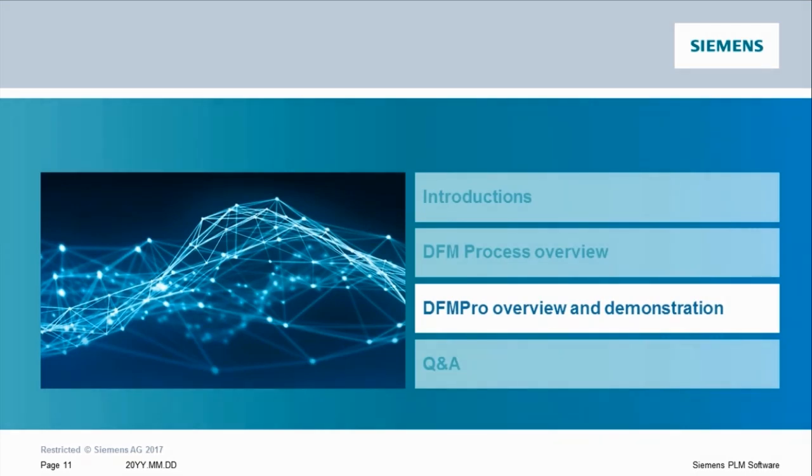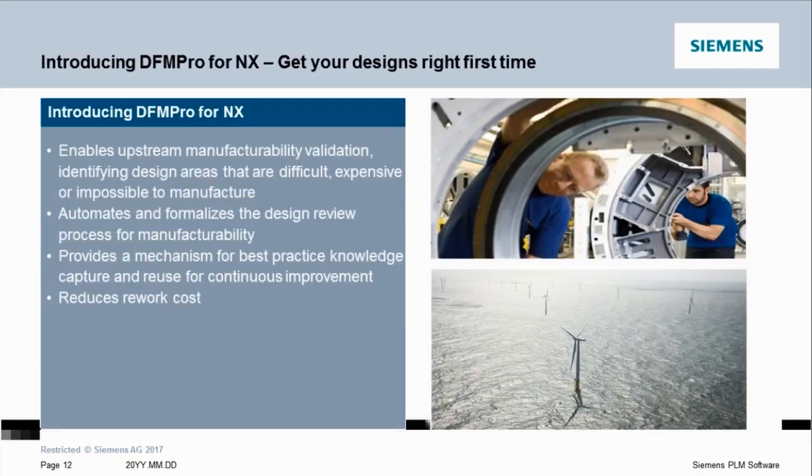So this DFMPro for NX is a software which is enabling the manufacturability validation for the design engineers. That means it gives you some suggestions and recommendations on some areas of the design which may be more expensive based on the kind of features that it has, and maybe sometimes it is, we cannot say impossible to manufacture, but going to be more difficult to manufacture.